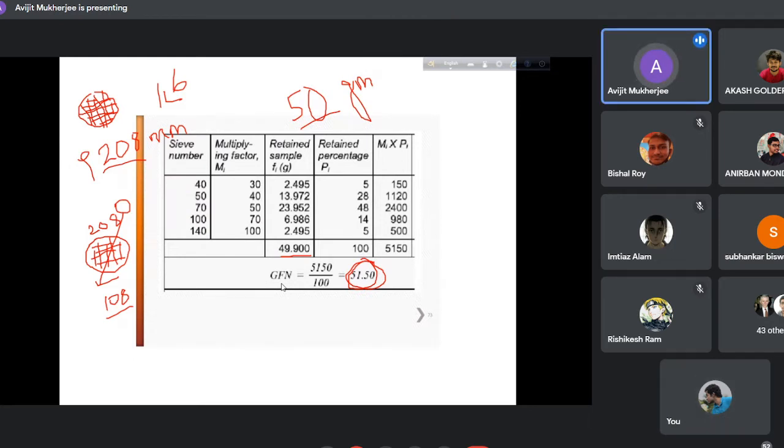What will be the exact definition of grain fineness number? So that is what I said: a grain fineness number indicates that if a standard mesh size of 0.208 millimeter were divided into an equal number of equal spaces, then the total sample would just pass through that net.